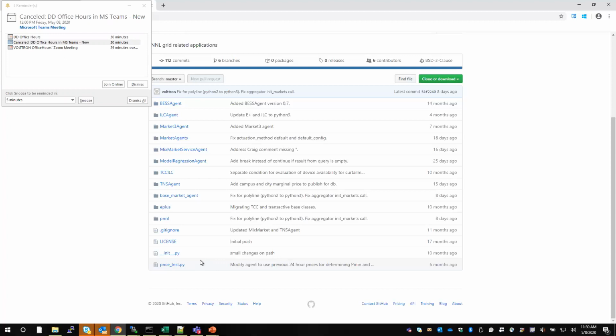And you can target that to specific VAVs or specific zones if you desired, but we've never done it for the use case that you're mentioning, where we want to just turn off periodically throughout the day. But that could definitely be accomplished using that mechanism. You just have to put a little bit of thought and modify that messaging agent that we've created to, instead of just firing whenever it starts, fire based on some schedule.